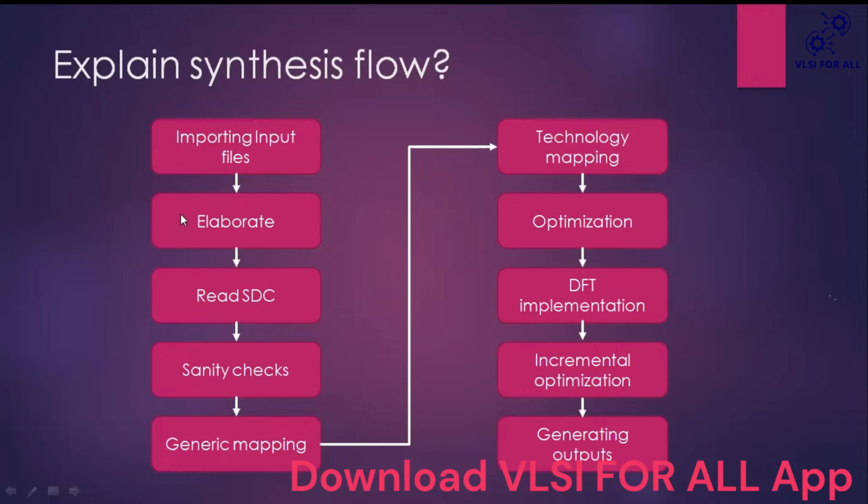In this elaborate stage, the tool also tries to remove all unwanted code in the RTL, like assign statements. If there are any combinational loops in the code, the tool will remove all these statements from the RTL code.